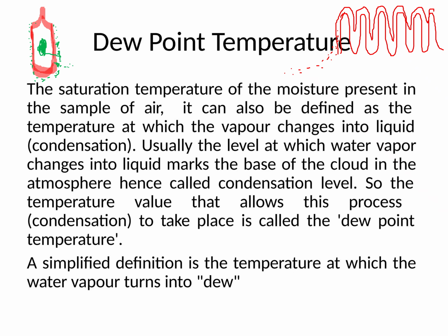refrigerant. So as in this scenario, something cold is inside the cooling coil and surrounded by water moisture. Okay, this moisture will be converted into droplets. And you know, from the air conditioner sometimes we see that a pipe is coming out with water. Actually, where does this water come from? This water actually comes from our exhaled moisture. So this is the dew point temperature. This dew point temperature is important for understanding air conditioning or refrigerator functioning.